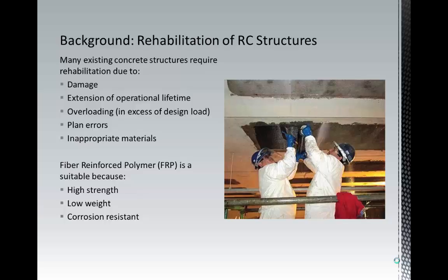Unlike the steel reinforcing, which was formed in the concrete members during construction, the reinforcement used for rehabilitation must be externally fitted. This is one of the reasons why fiber reinforced polymer, referred to as FRP, has become a potential reinforcing material, as it has high strength, is non-corrosive, is light in weight, and is convenient to work with as it can be cut to length and formed into complicated shapes on site.